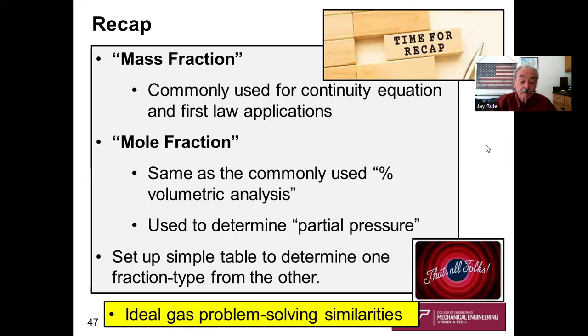And so now we have reached the recap for the video. So mass fraction, what do we remember about that? Commonly used for continuity equations, let's say open systems, and first law applications. So to determine R of a mixture, CP of a mixture, CV of a mixture, you're using mass fractions, okay? Mole fractions, same as the commonly used percent volumetric analysis.